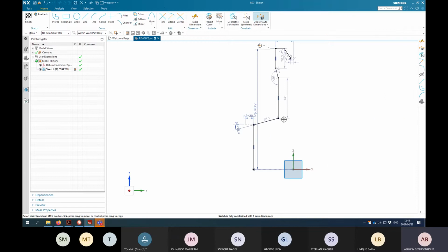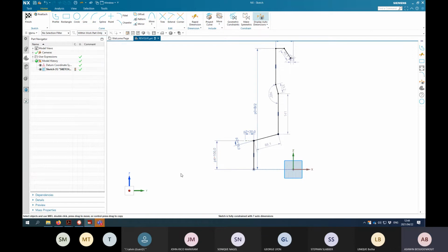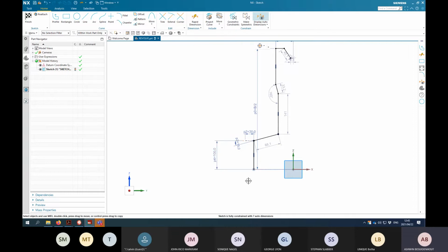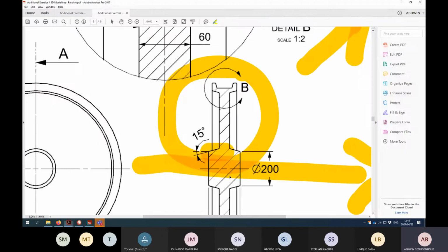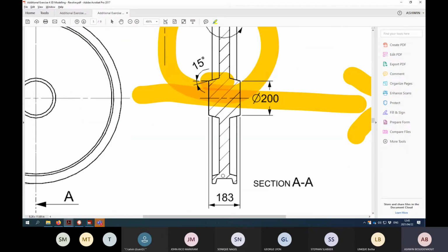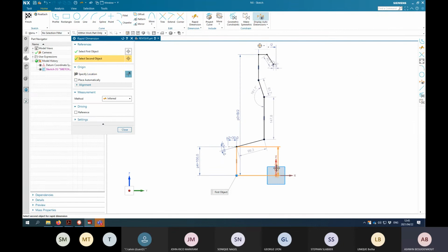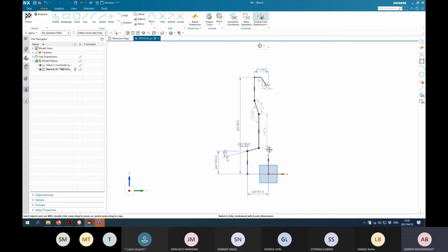So there's a 200 here. Again, I like to define the dimensions as it's given. I know it's a 200, so I can just type in 100. But because I like it, now if the 200 changes, I know exactly, oh, that's the 200 that they're referring to. If it needs to be 300, okay? That's why I'd rather go through the whole exercise of doing maths, even though it's not necessary. Okay, so now I have done this sketch. I got all of the information. Oh, there's another thing. This one here, 108. Then again, same principle. Divide by 2. Okay, so now I know.